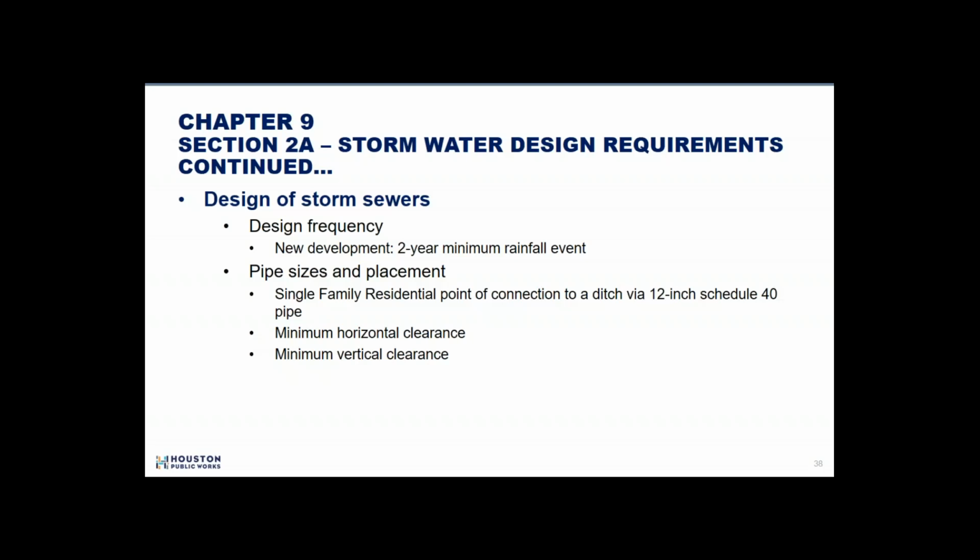So if you do have a yard drain, you basically will have to transition into a 12-inch pipe before it gets into the roadside ditch. 4-inch pipes are still going to be allowed to go through curbs for drainage of single-family residential property of less than 15,000 square feet. So that's still in the manual.